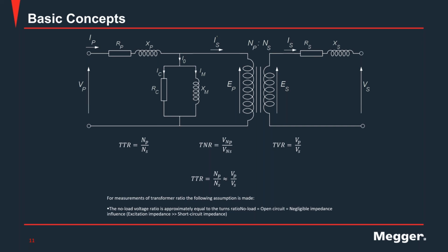That is not something that I will find on the nameplate or in the maintenance manual of the unit. Typically, as end users or the individual running the test, I don't know that number of any transformer. So what we are actually measuring in the field is the transformer voltage ratio, right? The TVR indicated in that last equation on the right.